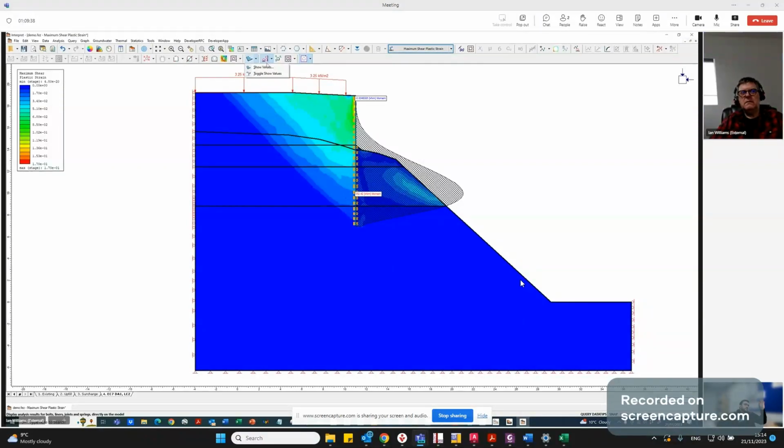Is that without taking into consideration a lot of slope stability things, just analyzing the wall, basically? For something like this, Wallop isn't really well suited. I mean, you can put berms in there and what have you, but they're fudges. They're not rigorous in the way that a finite element code is, where it properly represents the geometry of the slope.